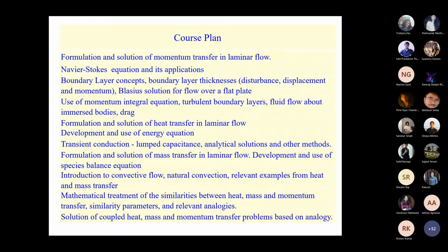And what is happening at the boundary is characterized by the convective heat transfer coefficient, which depends on several factors, such as the condition at the outside and so on. So it's h, L, and k: h being the convective heat transfer coefficient, L the length scale of the object under consideration, and k its thermal conductivity. Together, they provide us an idea of whether or not we can use the lumped capacitance model. So hL/k has a name.